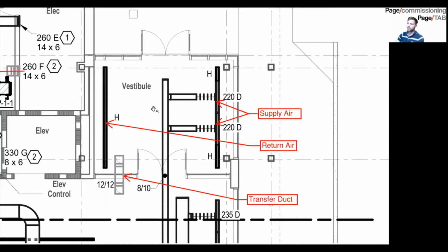After arriving inside the vestibule, I could hear excessive noise on these supply diffusers. So more than likely, airflow is not overflowing in here, right? The next thing I did to troubleshoot was open this set of doors here, and I asked one of the guys who was meeting me on site to open this door here.